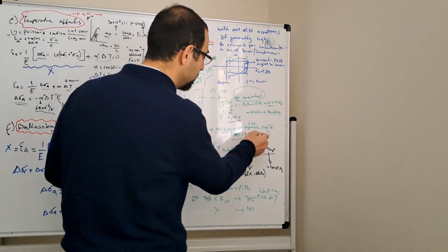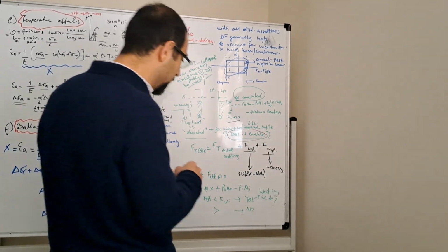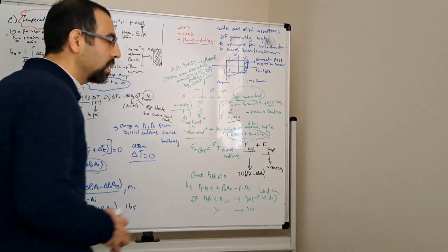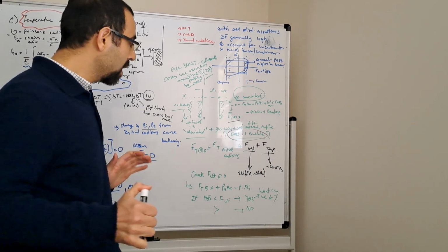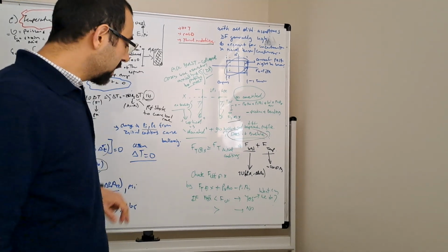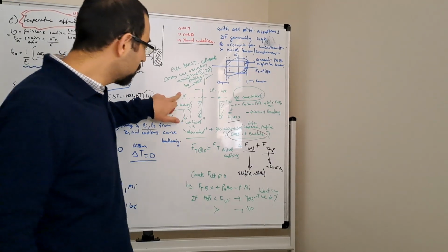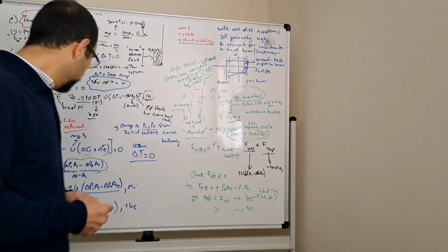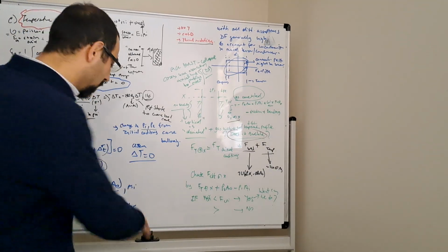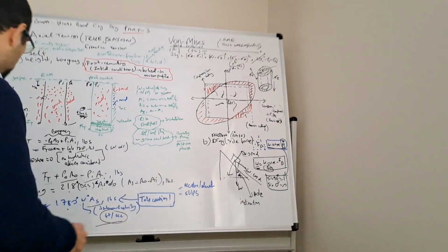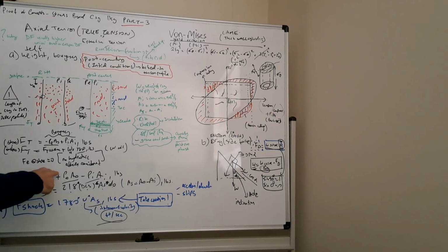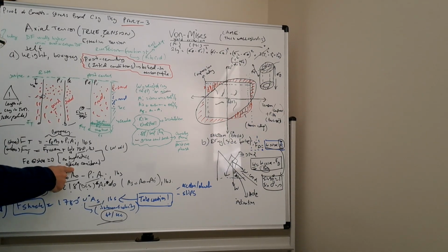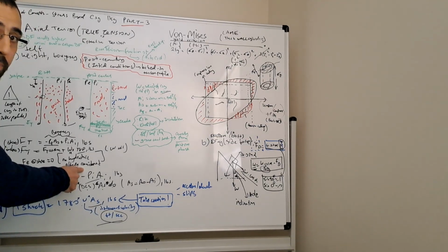So another question: does it buckle? I mentioned in my LinkedIn post that I'm going to briefly touch on buckling, but I'm not going to go deeper into helical or sinusoidal buckling, critical buckling load, etc. At X we calculated our true tension. What we need to do, as we mentioned, is go back to the effective tension. So we take the true tension, add the outer pressure times the outer area, and subtract the inner pressure times the inner area.